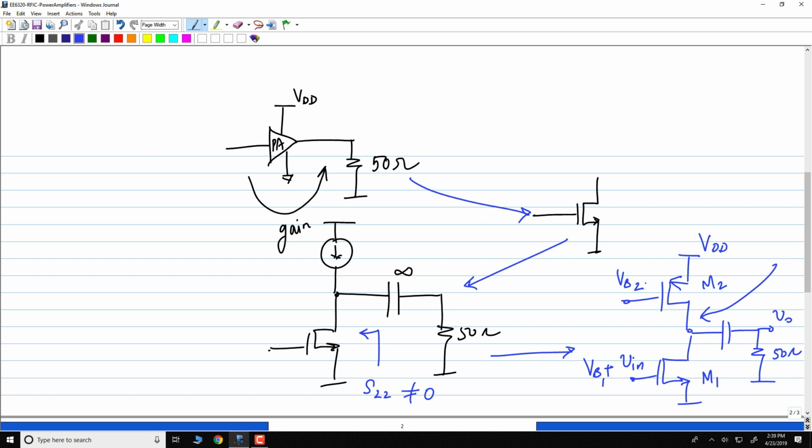Now, in the case of the LNA, let's say a common source LNA, you're trying to do input matching. Maybe you feel you anyway have to increase CGS, so you might increase the length anyway, to get a higher value of LS. But of these M1 and M2, M1 definitely is going to be minimum length. M2 is just a current source, that will be longer length.